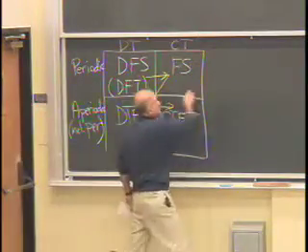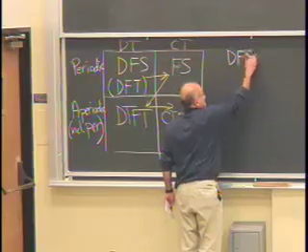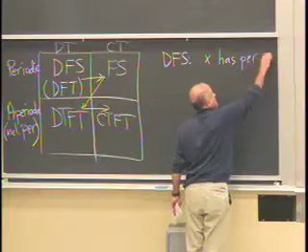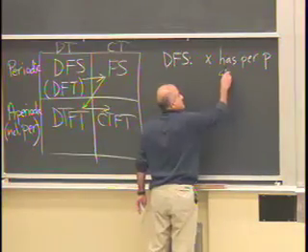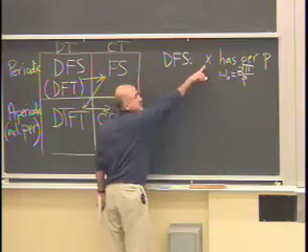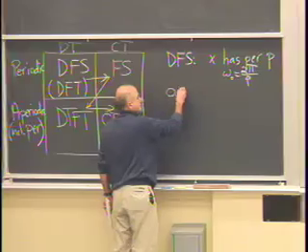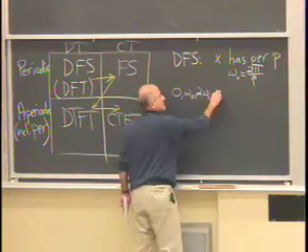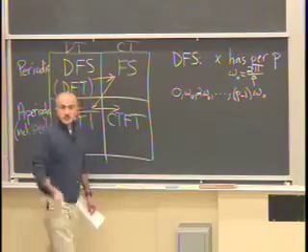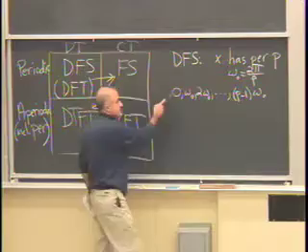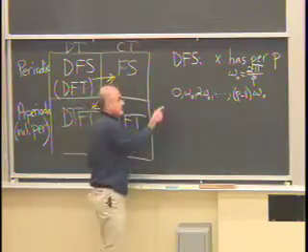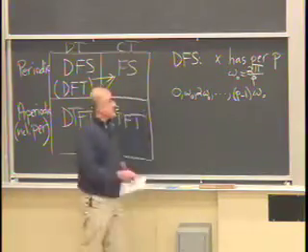So for DFS, x had period P, and fundamental frequency 2 pi over P. The frequencies that could be present in x were 0, omega naught, 2 omega naught, all the way to P minus 1 omega naught. It's a discrete set. And it's not just a discrete set, it's a finite set. I can count them. There are at most P frequencies in a periodic discrete time signal.